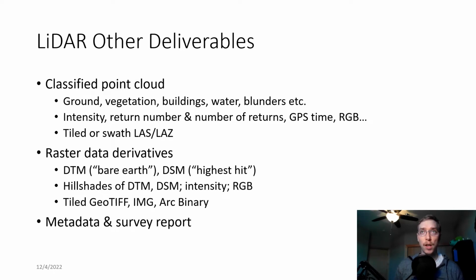I will create a digital elevation model, a digital surface model, a slope percent, a slope degree, and a hill shade. A point density raster is another one that I'm very interested in: when we have our raw LiDAR, how many points are in a certain area. I'll show one of those here in a little bit. I also do things like vegetation height. I'll take our digital surface model and our digital elevation model and subtract the two. Wherever it's 0, I remove that, because that means it was bare ground once and it was bare ground again. So I create a vegetation height raster so I can do things like calculate biomass on the surface. There's really no shortage of things that I do with LiDAR at this point, and that's because there's no shortage of things you can do with LiDAR.